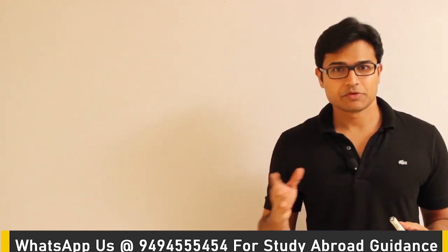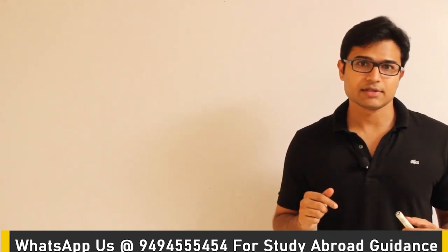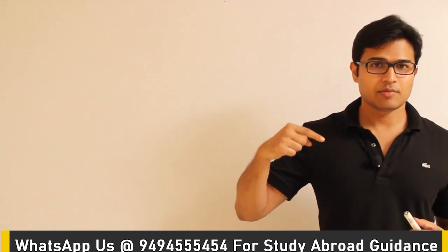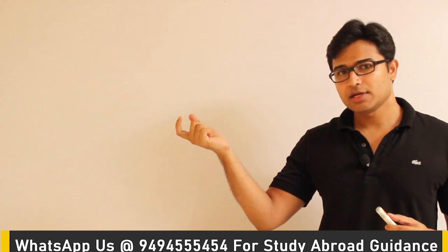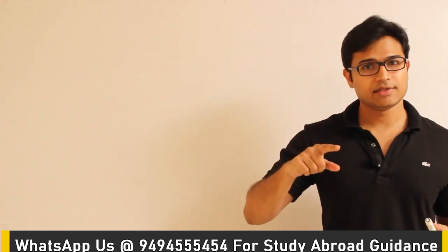Irrespective of whatever the instruction it is, if you have to execute it, you have to load it into the instruction register. Therefore, you have to definitely do those two actions. One is sending the program counter into the address register, and the other one is loading the word from the memory into the instruction register. These two things have to be done whatever the instruction it is. That is why I was directly connecting the timing signal to those control inputs, so that these things will happen automatically at T0 and T1.